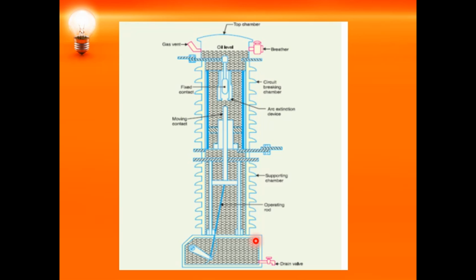And the moving contact tube is actually fixed, it is a fixed piston. So when the moving contact moves downwards, it forces the insulating oil. When the moving contact gets down, the oil enters the chamber and quenches the arc, or removes all the ionized particles. That is how the arc gets quenched. So this is the minimum oil circuit breaker.